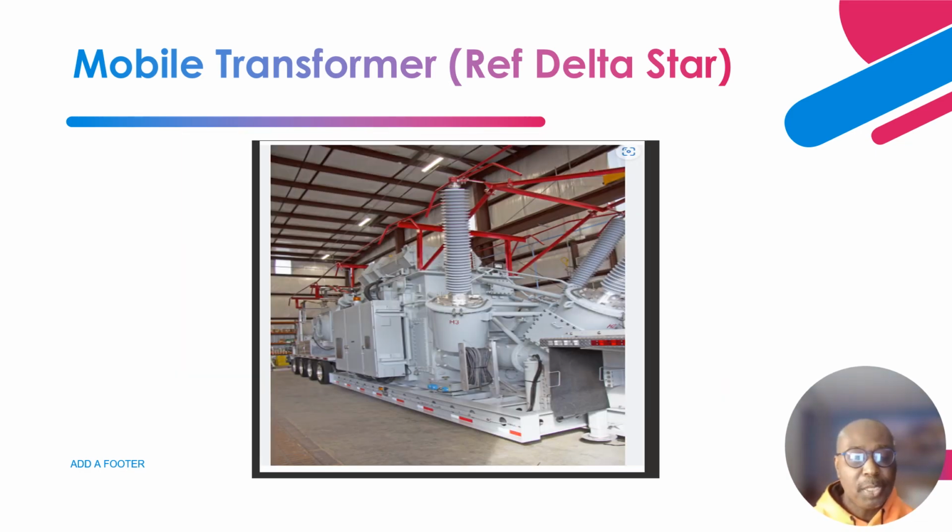Okay, so this one is a closer picture of how these bushings look. Like I told you, the high voltage side is tall, big. So this one should be a 115 kV, 230 kV, or 345 kV, whatever. That's how they look. And this one is the bushing turret. It is filled with oil and has CTs. Let's say it could have 2 or 3 CTs.